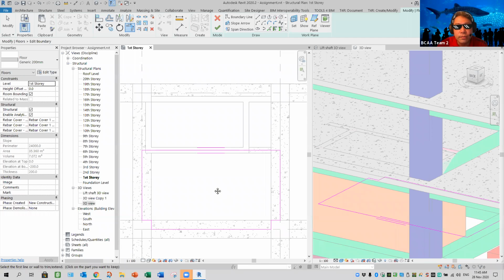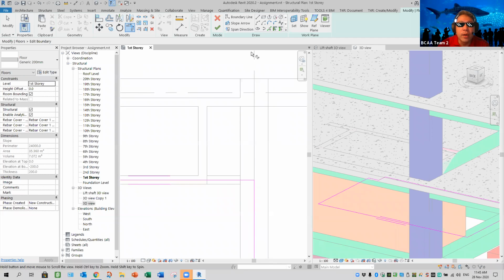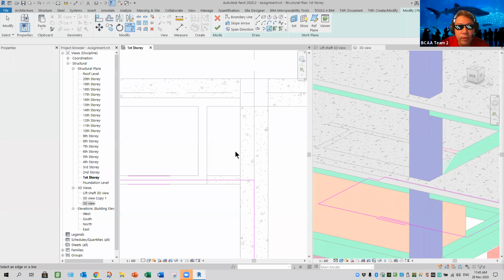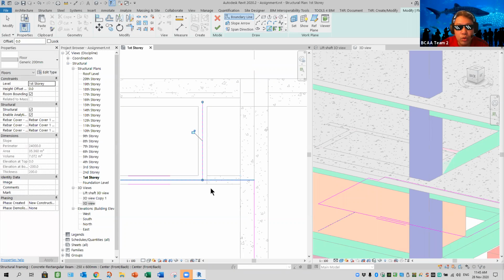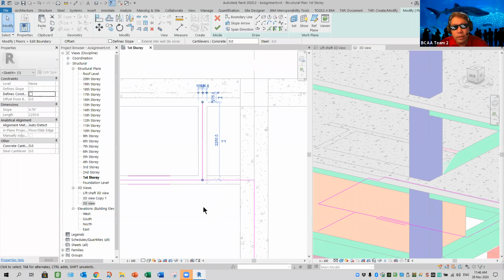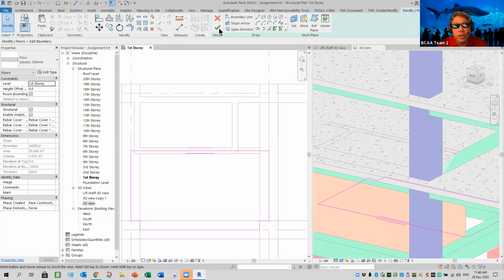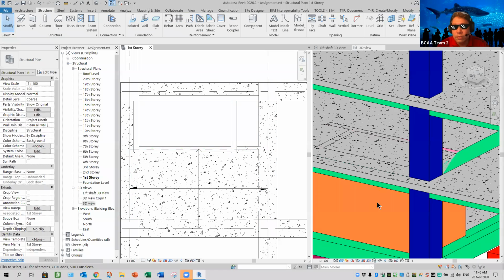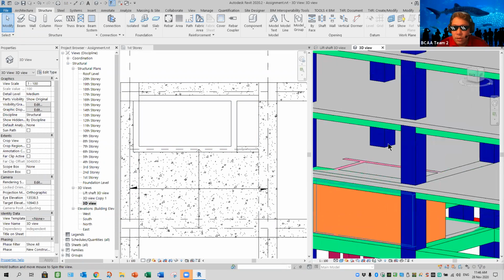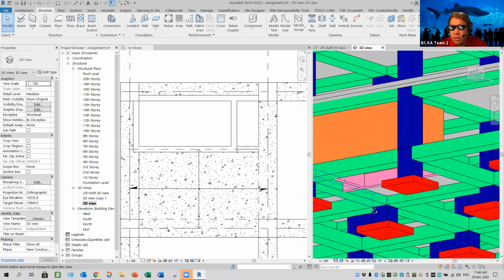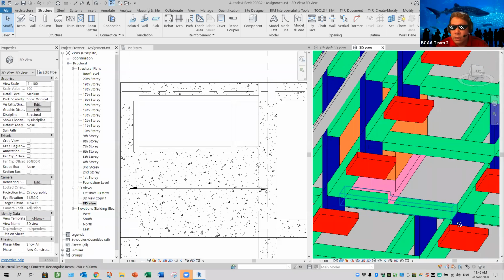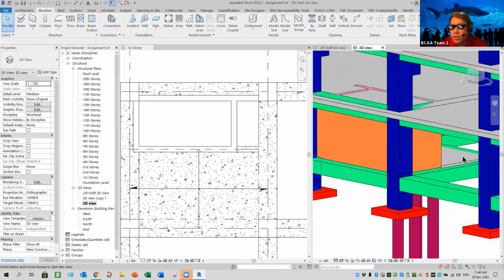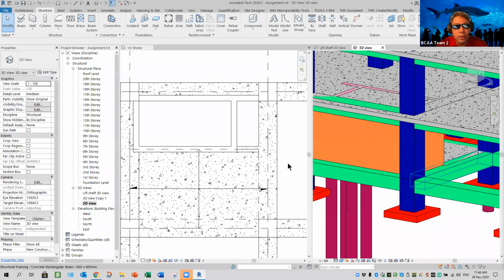So it should be like this for this slab. Then as for this slab, there's a beam there, right? You should be doing half of this, but don't do them together. It'll prompt you there's an error. So you're going to do one slab at a time. Okay? So this one piece, you finish. Okay, so this is the slab that we're supposed to see, which is here. I believe you still see the overlapping.